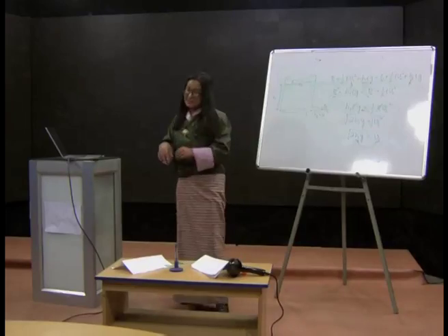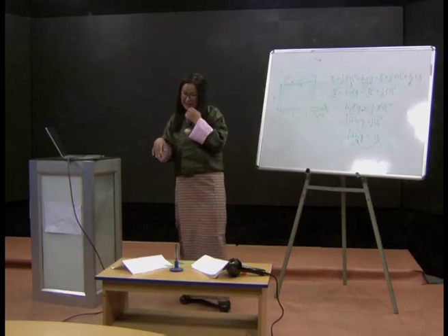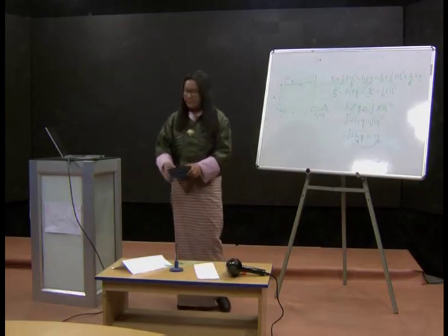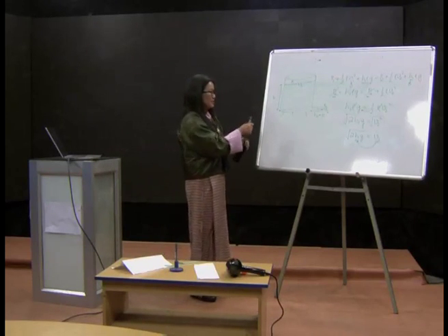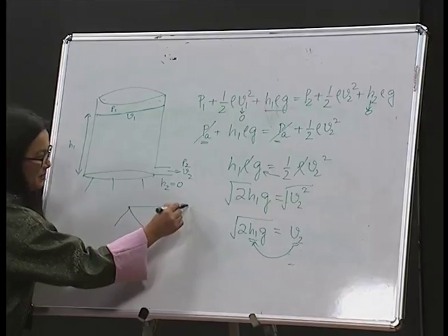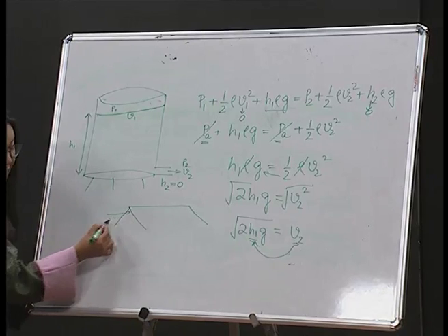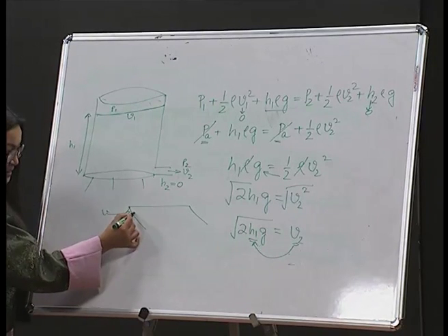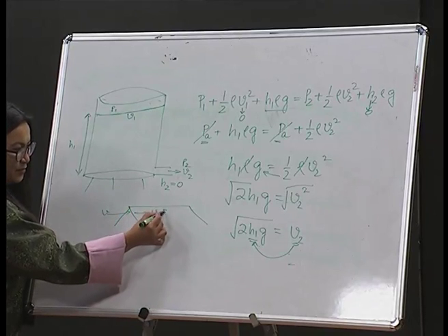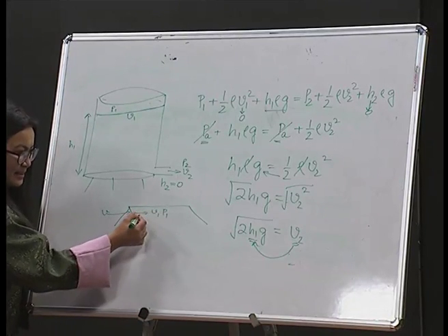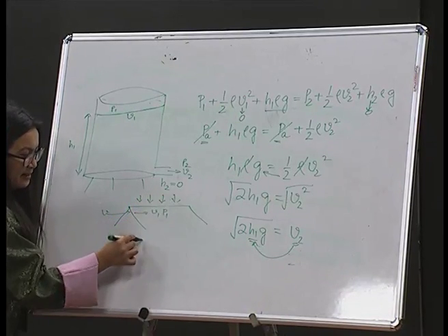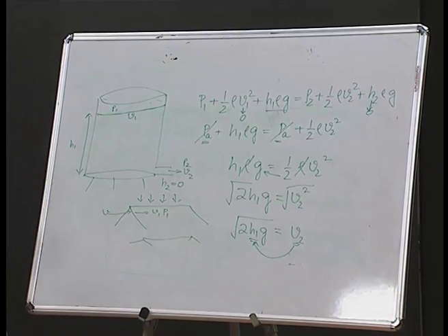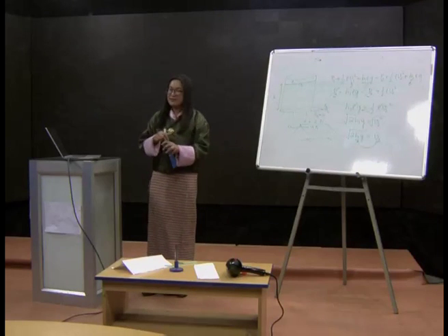So, what did you see? The paper is becoming flattened. Now, what is your explanation? Okay, let us check whether your explanation is correct or not. So, this is the paper, you are blowing high velocity wind inside. So, V1 is high, P1 will be low. So, pressure inside is less, atmospheric pressure outside is more. So, that will press down, that is why it becomes flattened. So, that is the reason. I hope you got the same reason, and if you got it correct, very good.